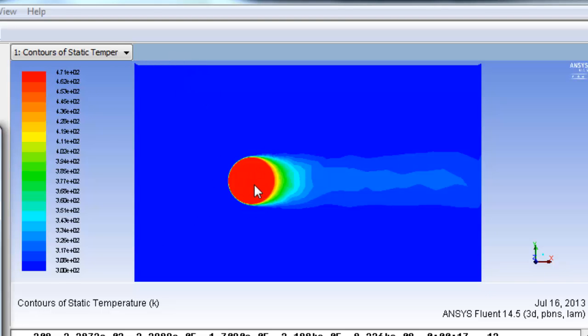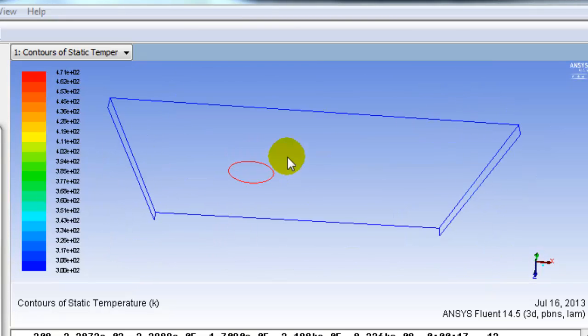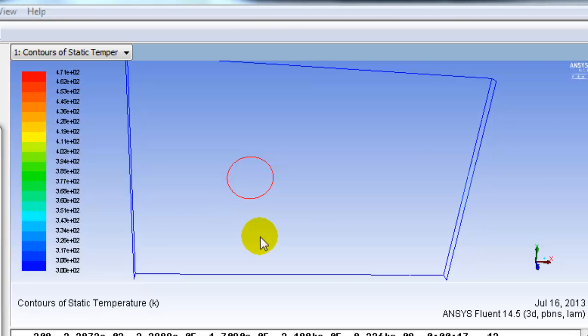It's hot everywhere because we had heat generation across the whole volume. You might want to just have the heat generation in an annulus around the outside, so potentially we could go back and chop up the disk so we just had heat generation where the pad was, but that's a refinement. Fluid 300, so that looks right. So fluid at 300, a hot disk, so then we have our hot wake behind here. So that's looking actually quite nice.